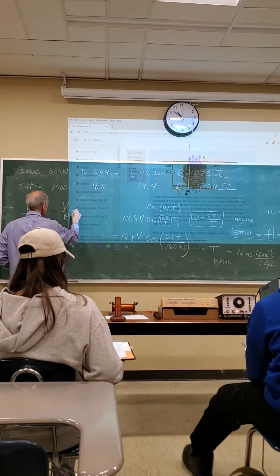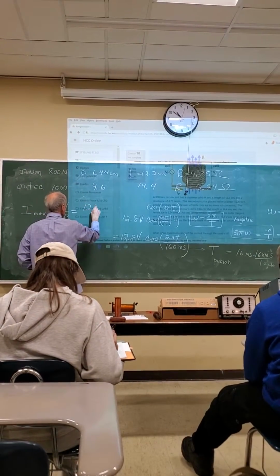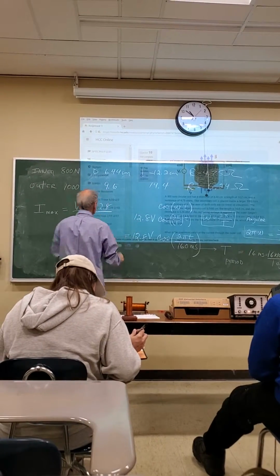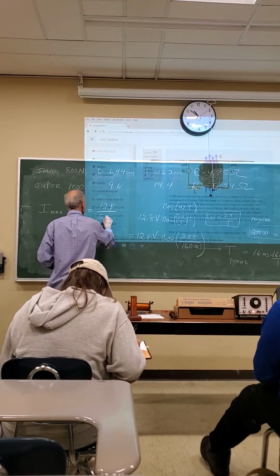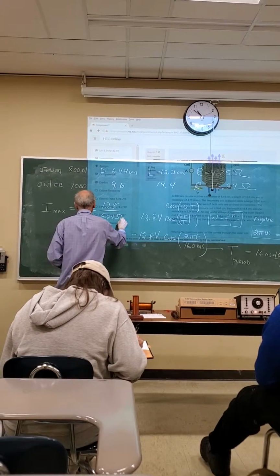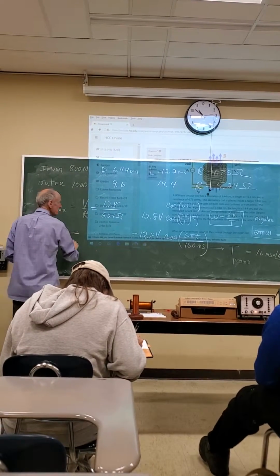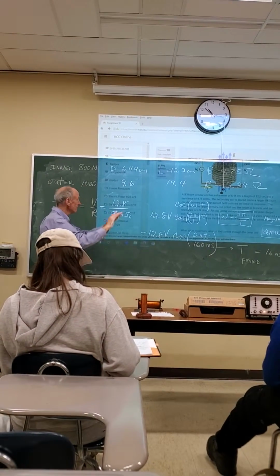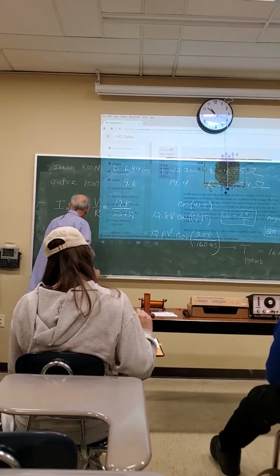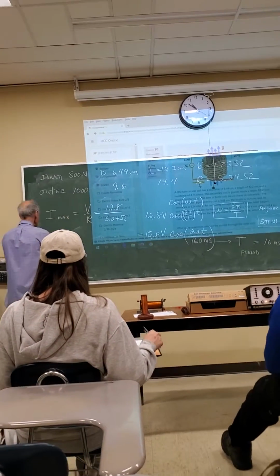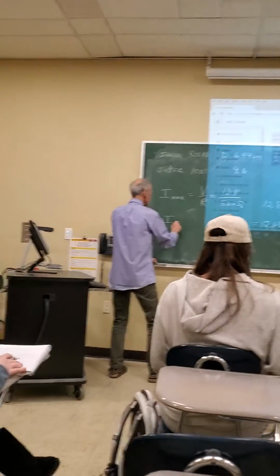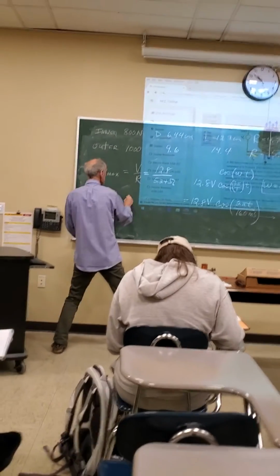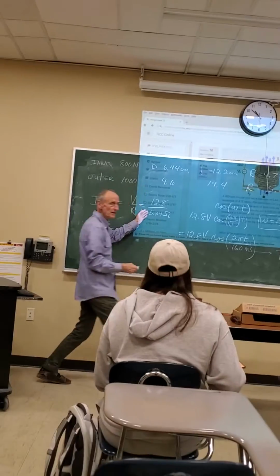So anyway, the voltage we're applying is 12.8 volts and the 5.24 ohms, and so that will give us the maximum current. And since the current follows the voltage, we can write that the current through that outer coil is going to be simply, do you have a number for that?